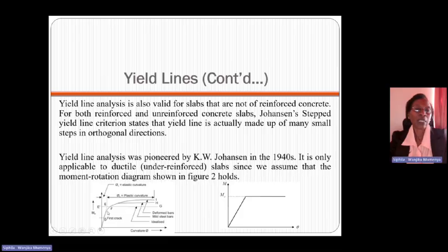When you have the idealized case, it is where you go soon after the elastic limit happens. Then you have the plastic plateau. And this is still the moment curvature. For the idealized, you have a straight elastic, and then it goes into a plastic deformation.